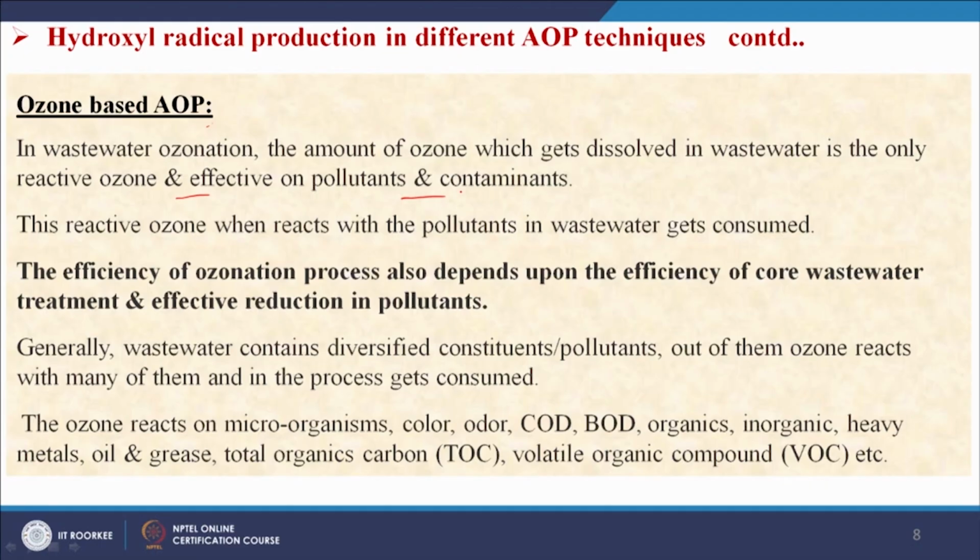The reactive ozone, when it reacts with the pollutants in wastewater, gets consumed also. The efficiency of the ozonation process also depends upon the efficiency of core wastewater treatment and effective reductions in pollutants. So, whether it is ozone only, or there is some UV or H2O2, or Fenton etc., depending upon the environment, the efficiency of the hydroxyl radical formation will vary.